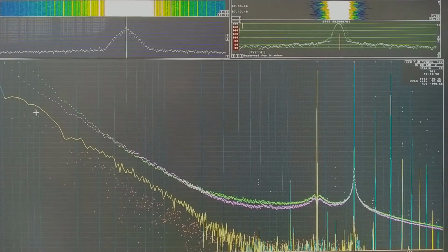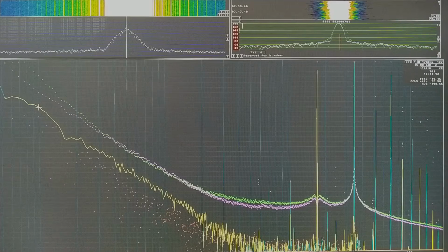I have changed the size of the Fourier transform that computes the phase noise, and that made a difference. Now I see 98 at 0.1 Hertz offset, but the statistics is very poor because with this large transform, measurement becomes very slow.